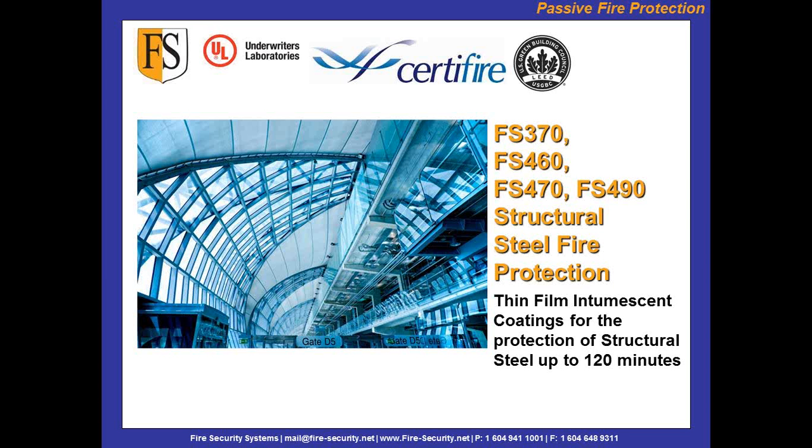So a thin film coating is really clearly what it states. It's thin. It can be anywhere from 300 or 400 microns up to 5 millimeters. To your second part of the question, how do we determine the thickness of the coating itself, it relies basically on what's called an HP/A or M factor, which is basically a section factor concept.